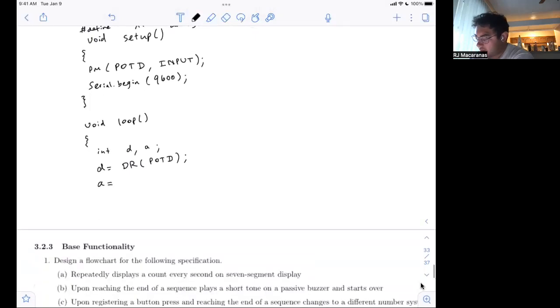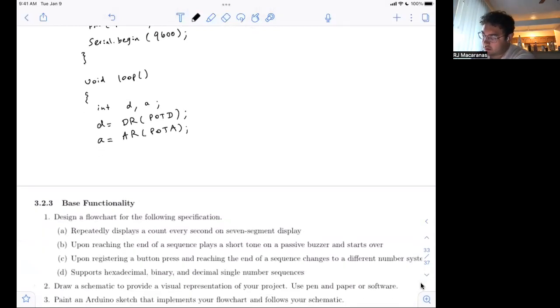There's our macro. So we do an analog read on our analog pin. And then we want to display it. So we print, let's just say, "analog". And then we Serial.println with a new line. This appends a new line character. So then we print out our analog reading.